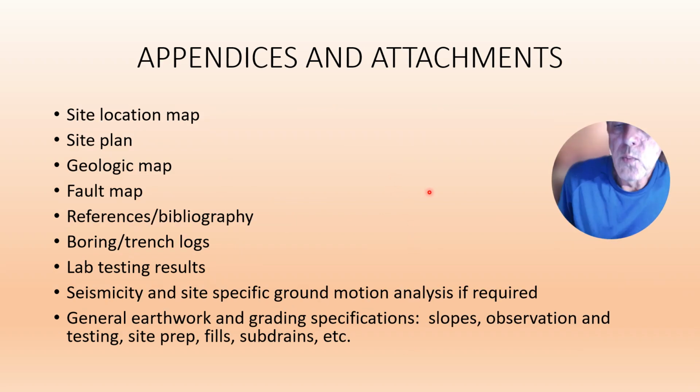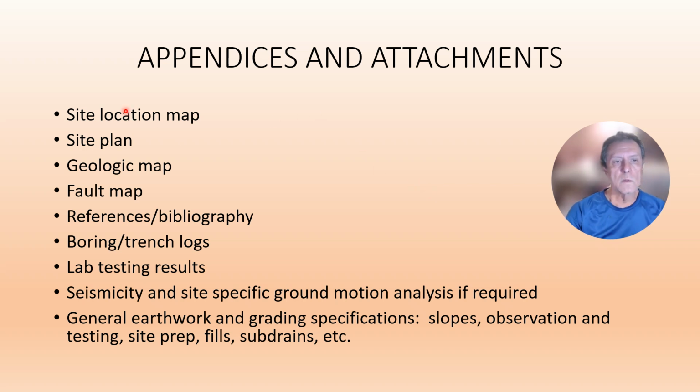Finally, every report should have appendices and attachments that include the site map, showing where the buildings, streets, etc. are, including grading plan, if available, the site plan, and site location, that means where you are geographically. The site plan itself shows the building layouts. A geologic map, obviously, is very important. A fault map showing any nearby faults.